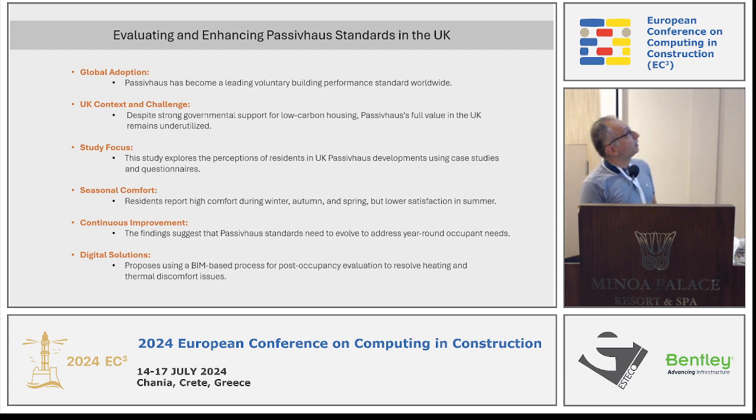So passive house has become a voluntary standard. Despite support for low carbon buildings, it's not a requirement. And I think a very important aspect here from a UK context is that there's been a drive for renewable energy, so maybe heat pumps, solar PV, or wind turbines. In reality, renewable energy isn't the same as energy efficiency. You can put more equipment on a building and bring it to zero carbon, but the building might not be energy efficient. So the study focused on exploring residents in UK passive house developments. Globally, I don't think there are more than maybe 15,000 homes or buildings that are passive house.